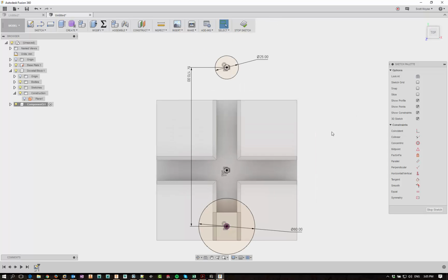Okay, now it's drawn that this is the tip. So if you left click on the coincident, and move around, then the line's going to rotate around that point that you've selected. But if you hold down shift, it will snap to tangent, which means that you can come over here and grab the tangent at this end, and now you've got a line that's between two circles and both ends are tangent. It's a pretty sweet little tip, that one. It's quite handy specifically for this type of sketch geometry.